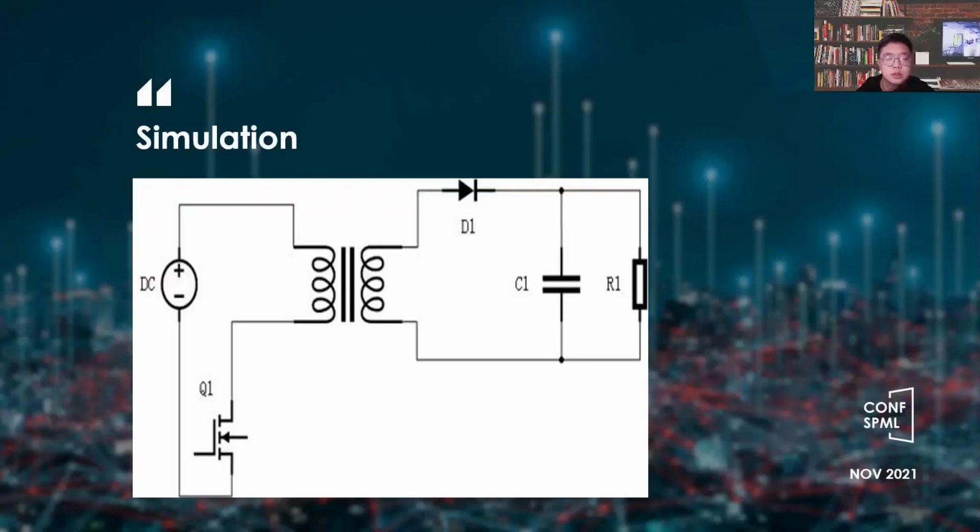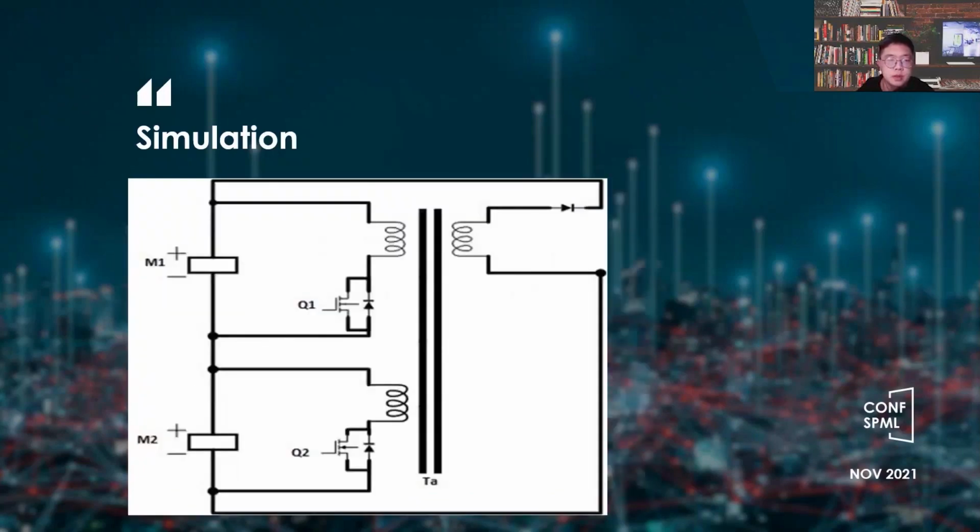As you can see, this is a very basic flyback converter. The flyback converter essentially replaces the inductor between the MOS transistor and the diode of the buck-boost converter with a high-frequency switching transformer to achieve electrical isolation. And this is what I do. Based on an active equalization of a multi-input transformer, the principle of active equalization of the transformer is analyzed and simulated.